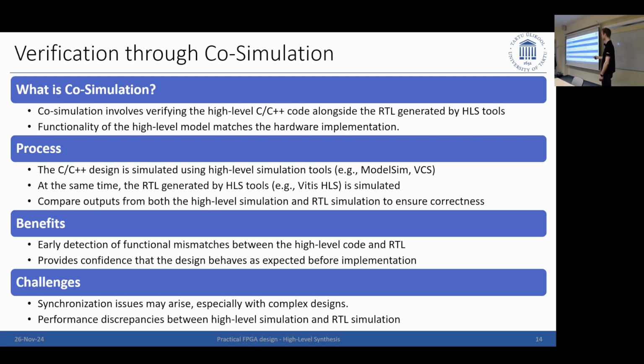It's also actually very common. Co-simulation, as an example, is sometimes used when people develop algorithms or encodings in VHDL. So you can write your Python simulation, your Python model of your algorithm, and that's how you develop it, right? You do your R&D: how do I do an algorithm, how does it functionally work? Then you let it run through your image or whatever it is, you get the result out. That's what you store, and that's what you then can compare. We had this in verification and simulation, and then you can compare that to your VHDL simulation output. That would be the ideal, and this does it automatically for you.